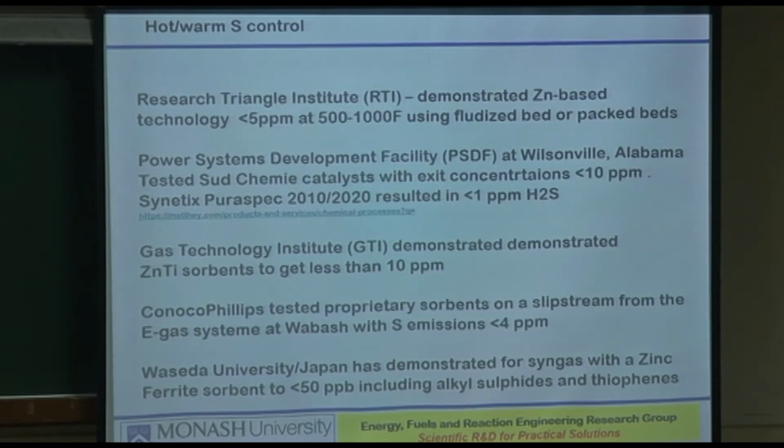Yes, that's right. So it all depends on how I am going to use the gas. Because if I need the gas at high pressure, obviously I will have to run the gasifier at high pressure. Otherwise, the only other alternative will be to run it at atmospheric pressure, cool the gas down all the way to ambient, and then compress it. And then you as a design engineer carry out the techno-economics, and then decide which one is more economical.